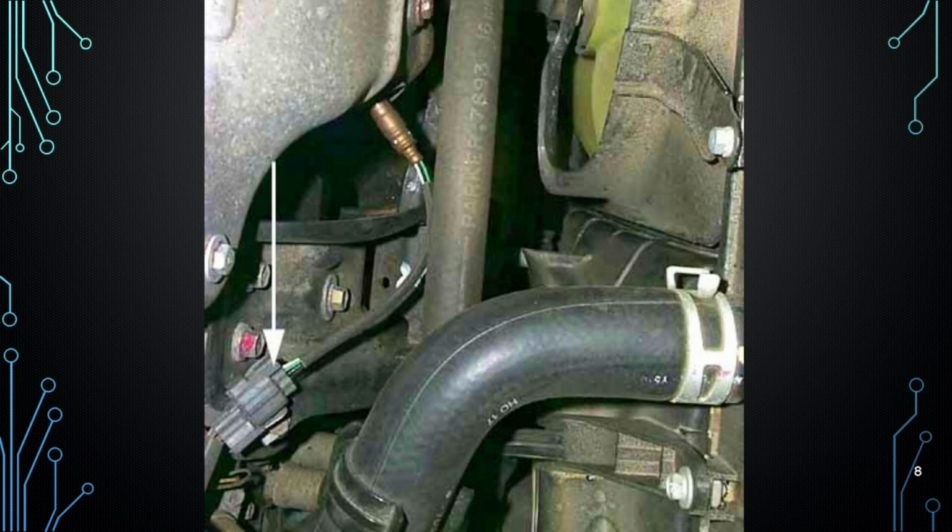That connector is likely for an oxygen O2 sensor. In older systems, a single wire O2 sensor only provided the signal. With multiple wires, you have a heated O2 sensor, commonly 3 or 4 wires. The additional wires power a heating element that brings the sensor to operating temperature more quickly, allowing it to provide accurate readings sooner. This improves emissions control, especially during cold starts.